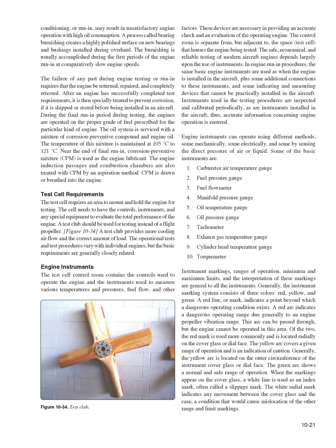A process called bearing burnishing creates a highly polished surface on new bearings and bushings installed during overhaul. The burnishing is usually accomplished during the first periods of the engine run-in at comparatively slow engine speeds. The failure of any part during engine testing or run-in requires that the engine be returned, repaired, and completely retested. After an engine has successfully completed test requirements, it is then specially treated to prevent corrosion, if it is shipped or stored before being installed in an aircraft.